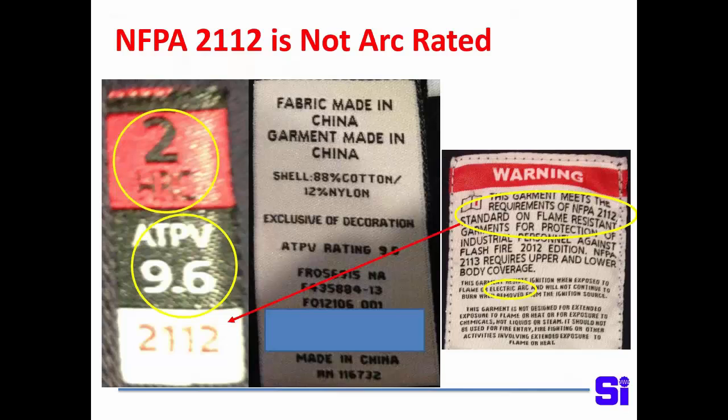And unfortunately, people are buying this equipment because it's a good price. And, you know, in all honesty, maybe it's fine. But if this guy gets hurt wearing this clothing and he takes his employer to court, his employer is going to lose a lot of money. So that's a really good deal on this arc rated or apparently arc rated equipment that is not arc rated is going to turn out to cost them a whole bunch of money.